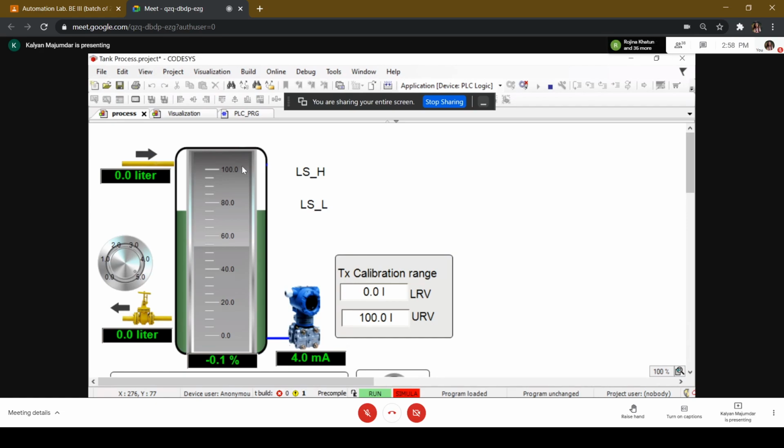So the inflow rate physically can have three different states. One is zero, for overload conditions or pump off. Maximum, when everything is normal and the pump is operating fine. And something in between zero and the maximum value, if the pump is operating but you have some kind of a fault in the water delivery system. So that is the input. The output is variable. It varies from zero to a maximum value. The maximum value depends upon what rate you'd be consuming water. Right?